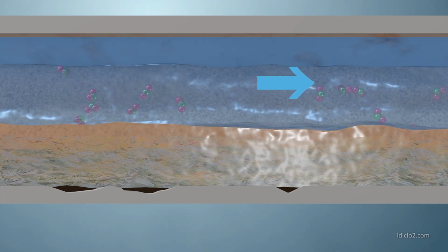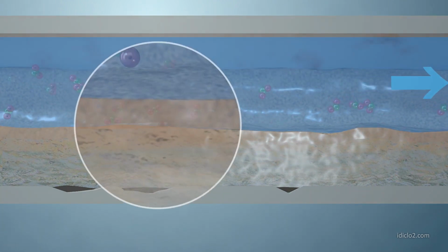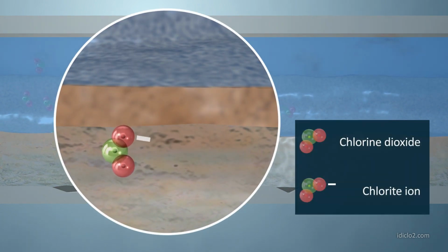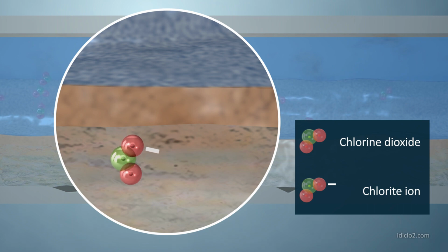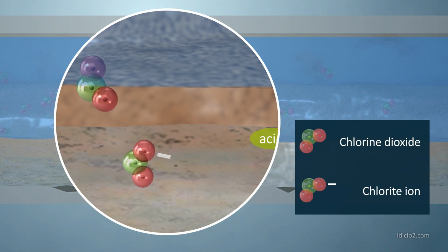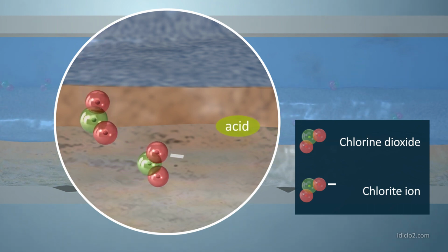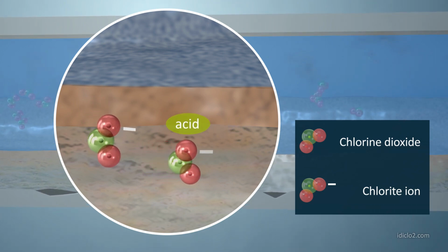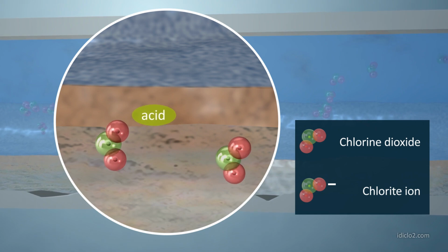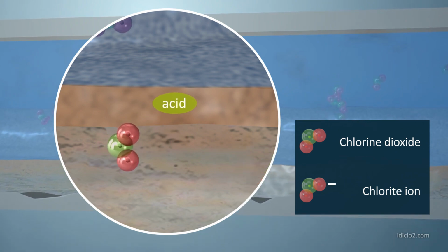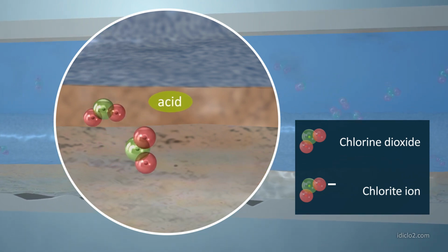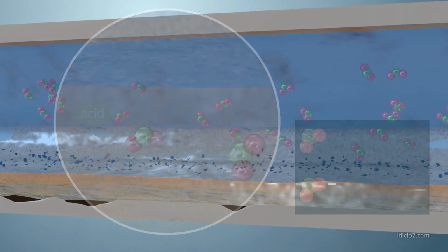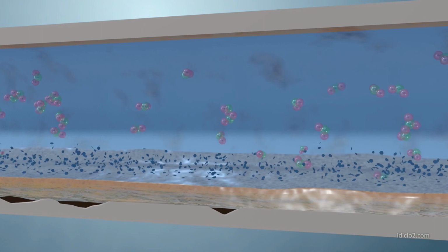In addition, as chlorine dioxide reacts as a biocide, chloride ion is formed as a ClO2 disinfection byproduct. When chloride ion encounters acids, such as those produced by SRBs and APBs, chlorine dioxide is reformed in situ. In effect, a cycle of chlorine dioxide consumption to chloride ion and a partial regeneration back to chlorine dioxide is possible in many biocidal applications, including biofilm control.